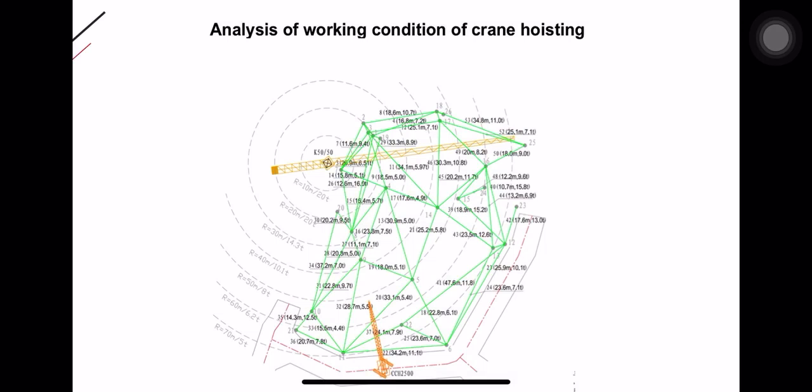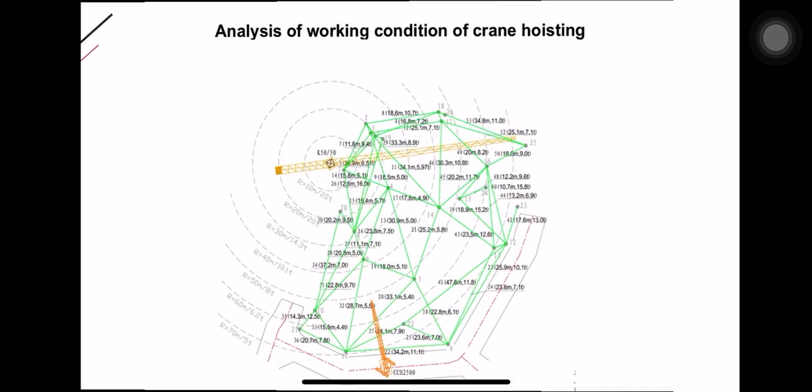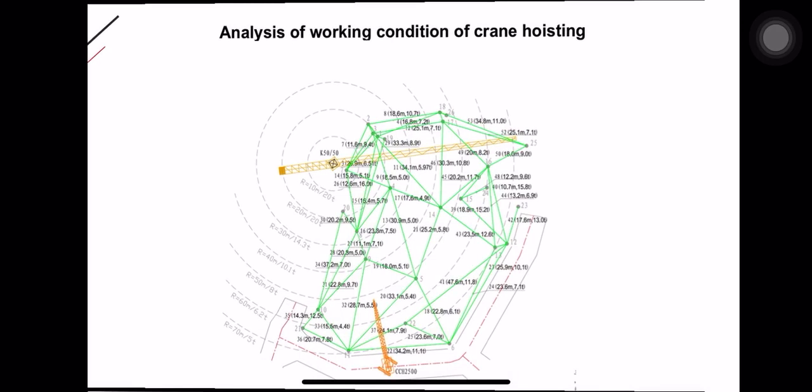The working condition analysis of the main beam of the multifunctional hall is shown in the figure below. The figure only lists the section widths of the beams with larger cross-sections and divides them into sections of 15 meters. Taking into account the weight of the corbels of the secondary beams, after the main beams are sectioned, they are all within the range of the crane.